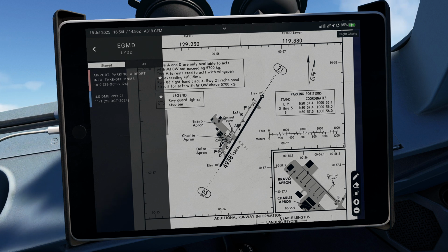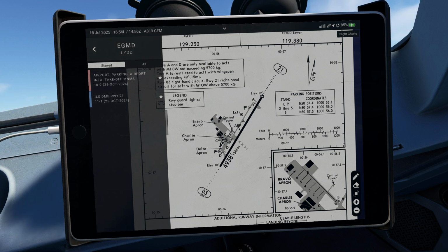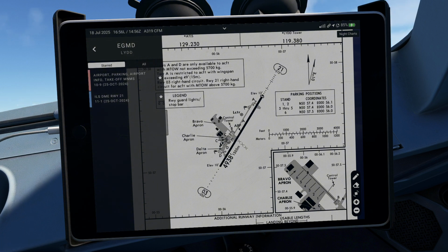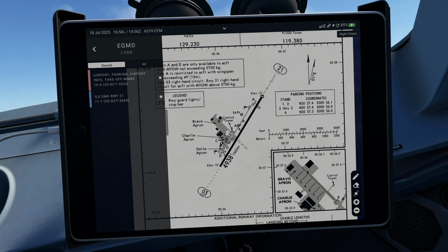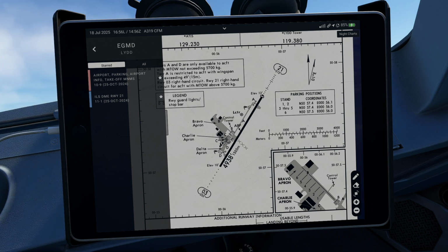This airport is not beneficial economically for the airlines. For example, because of the low landing weight and the landing capabilities and margins, they should carry less fuel, which makes diversion to an alternate airport much harder, with lots of limits.